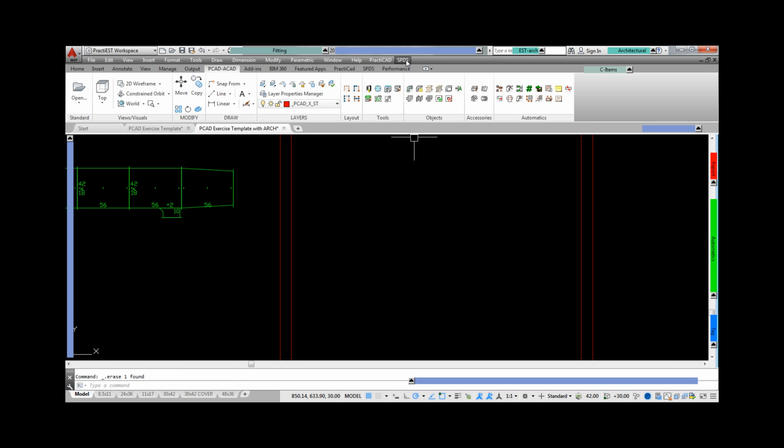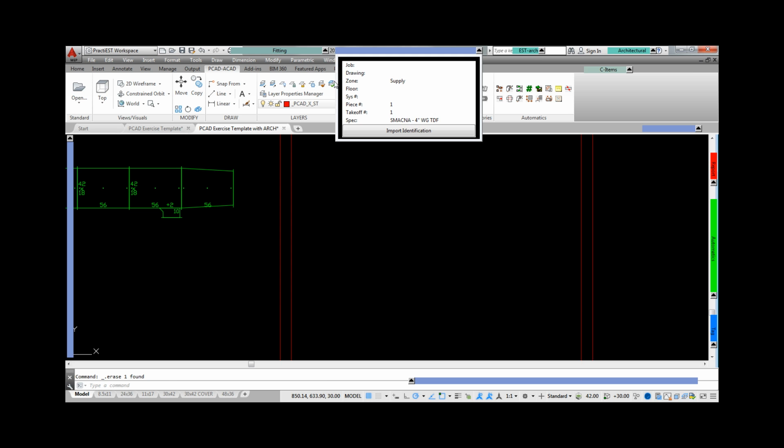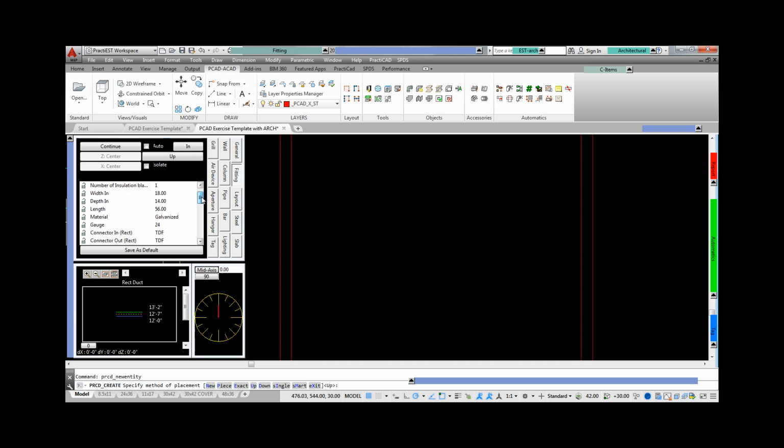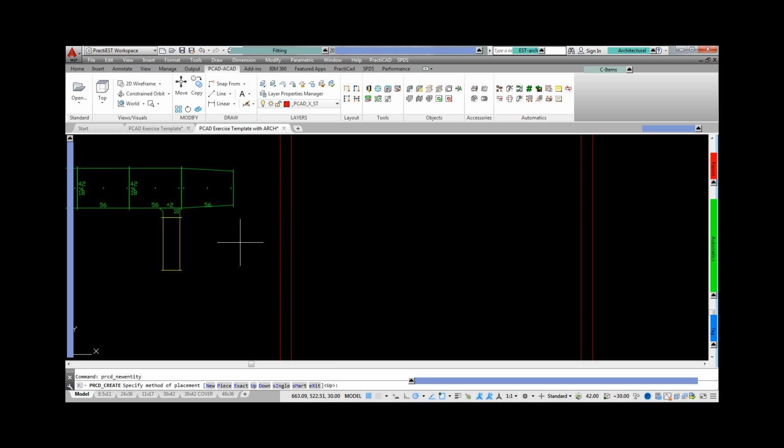With PractiCAD fittings and features, drawing has never been quicker. Look here as we simply grab a fitting and specification and PractiCAD updates everything we need to draw with. See how we can draw piece by piece and just snap to the fitting we want, and it automatically resizes and updates connections. We can also just key in C for continue and the fitting will snap to the last opening we used without having to find a hard to grab node or use an attacher of any type.